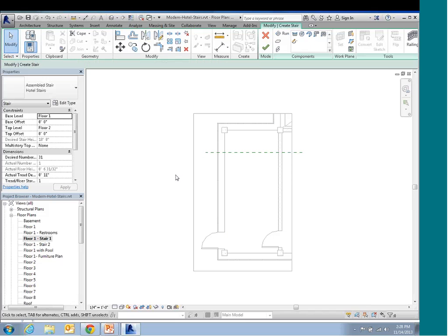And in previous versions, I had to do a lot of prepping for this. You know, like, how long is the run going to be, and where do I need to put all of my reference planes and things like that. Much easier now because we have the component stairs, and as you'll see just a second, I'm going to be able to move each component easily. So I'm all ready now to do my run, and I'm just doing a straight run right now.